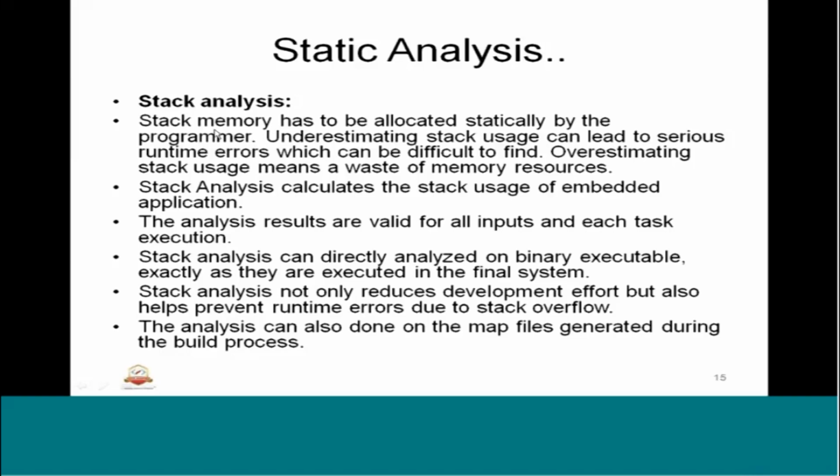Definitely embedded systems will have a stack memory, and stack memory has to be allocated for how much each embedded software fragment or the entire program is going to take. Underestimating the stack usage can lead to serious runtime errors. So we definitely need to have a safe bound of the stack memory, and allocation is very important, and we should make sure that the implementation of the embedded systems will not go beyond the stack memory.